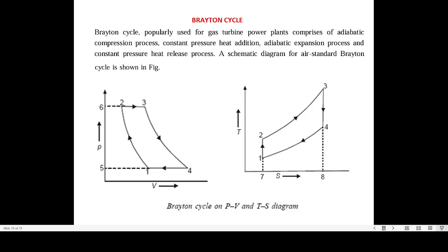If I have a close look at the temperature entropy diagram for process 2-3, I can definitely identify a tremendous rise in temperature from T2 to T3. So it is nothing but heat addition at constant pressure. The process 2-3 is constant pressure heat addition. The maximum, highest temperature in the cycle can be seen on the temperature entropy diagram at point 3, the gases which enter the turbine.